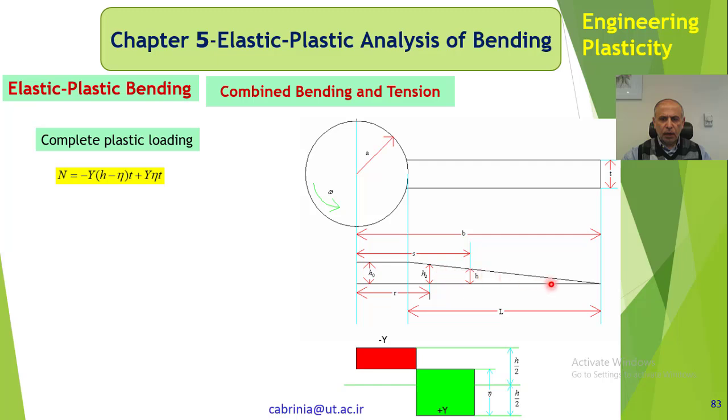Obviously, if we look at this blade as a beam, then because it is bending like that, there is a positive stress and negative stress. But because this beam is unsymmetric, the neutral axis position is not known. Okay, it's not in the middle of the beam, because there is no middle. Where is the middle? So we don't know.